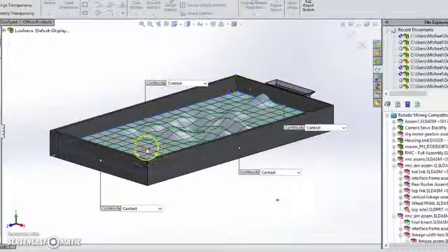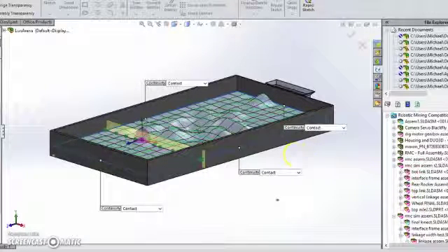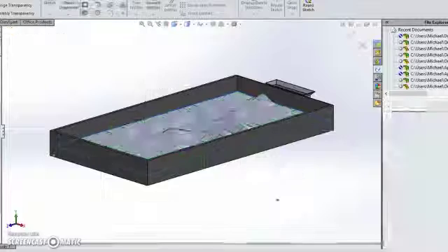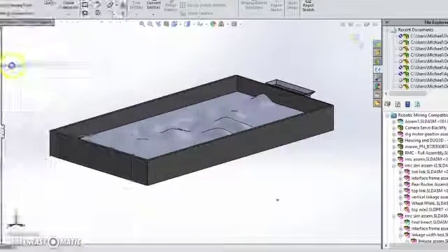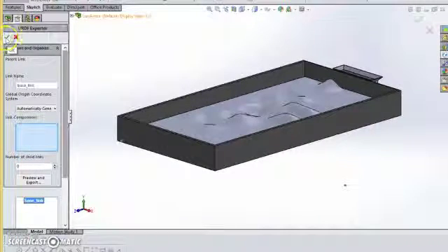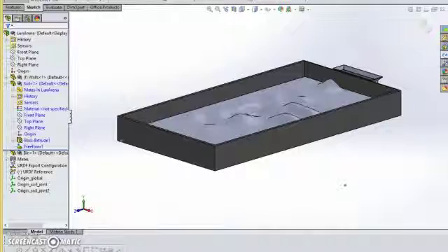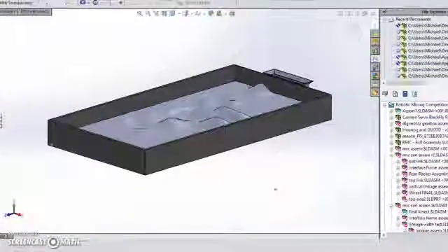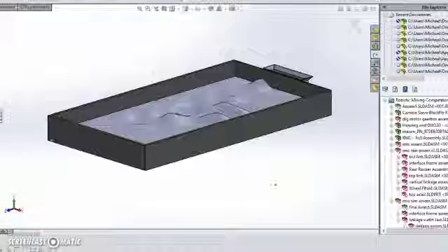You can make these meshes for the geometry in any way, through any software that you feel most comfortable with. In our case, we made it with SolidWorks using the Freeform tool to model the terrain elevations, which can be seen here. And then we exported it using SolidWorks to URDF export because of the ease of use, and then took the STLs created and made a DAE to apply some texture, which we'll show here.